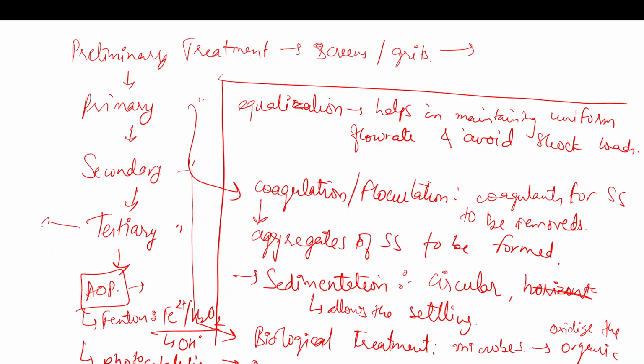Next, if you want to remove any specific pollutants, there are different methods which we had talked about, including adsorption, where you can adsorb a few pollutants including heavy metals. Then you can adsorb organics on a surface. Adsorption is basically the interaction of the pollutant, which is the adsorbate, with the adsorbent, and because of the forces they sit on the adsorbent surface, which causes the removal of the pollutant, right?